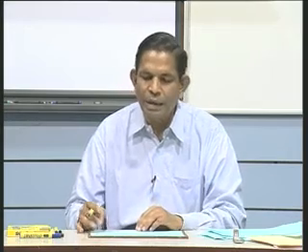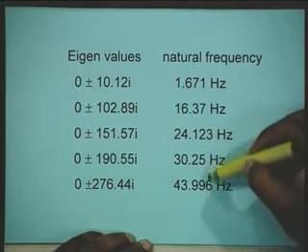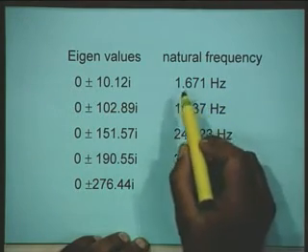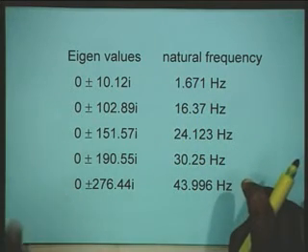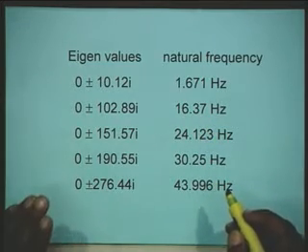Whenever this turbine generator is perturbed, torsional oscillations are produced, and the torsional frequencies are given like this. You can see here that for this 5 mass system we have these 5 different frequencies. The frequency 1.671 can be considered the system frequency, where the entire turbine generator mass oscillates with respect to the system, while the other 4 frequencies are associated with the different torsional modes of oscillation.